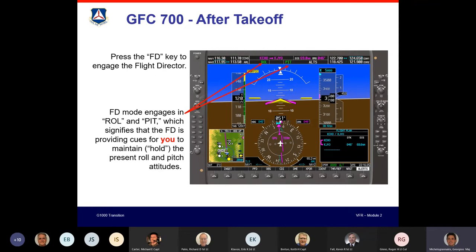That disengages the autopilot. You establish a climb manually. You can set the flight director, and then you can re-engage the autopilot. But you don't have to wait for 800 feet if you're doing the miss. Okay, since I mentioned that, how many ways are there to disengage the autopilot?